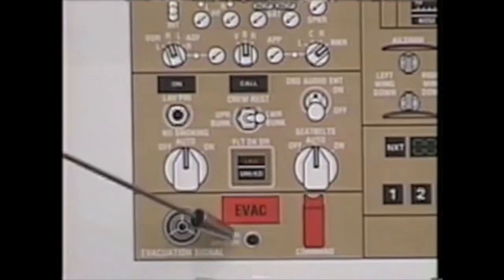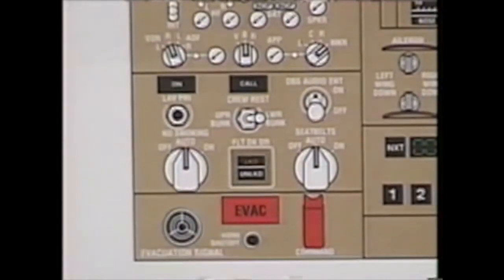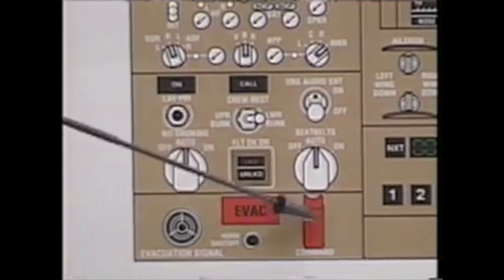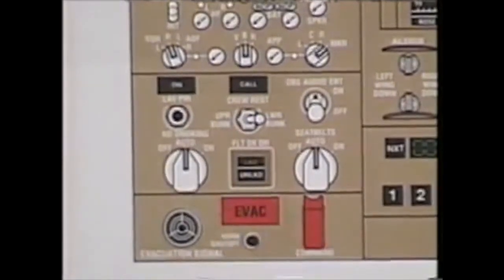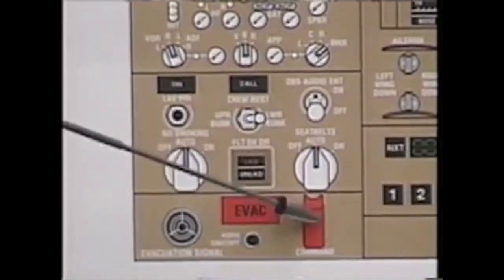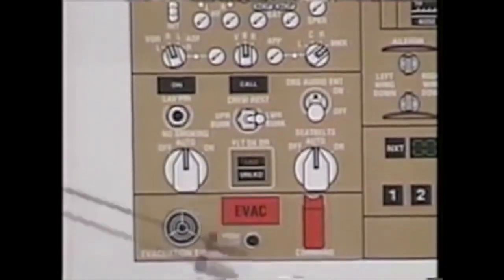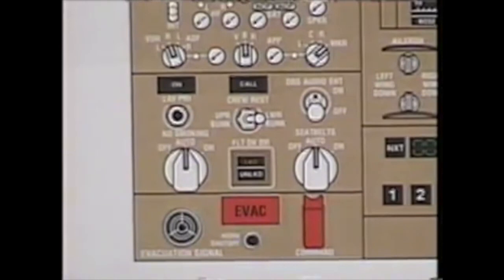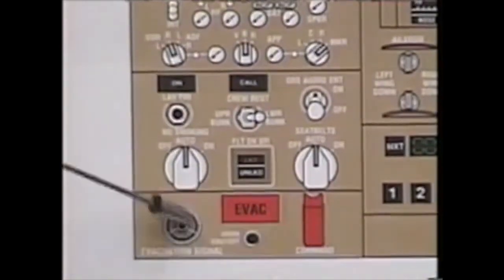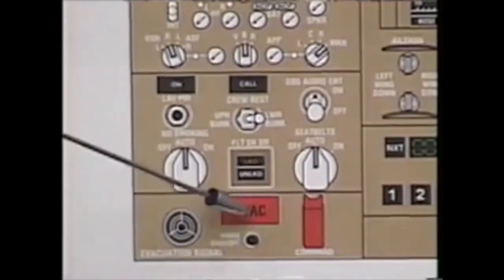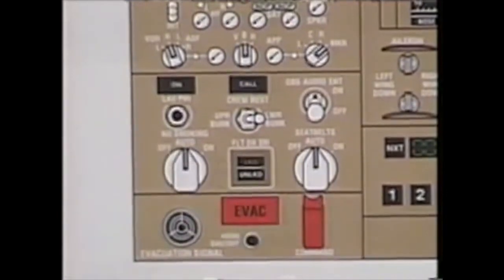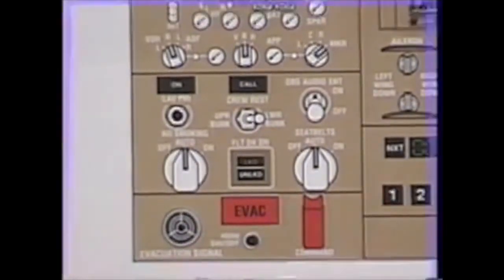Evacuation control panel, left aft end of the center aisle stand. Immediate action for evacuation is ATC notify. Call for the QRC. There are numerous switches throughout the airplane, flight attendants' positions at the doors, upper deck as well. Any one switch anywhere on the airplane will activate every light and every horn on every panel. Pressing the button on that panel will silence the horn on that panel only. The light continues to flash until all control switches are returned to normal.